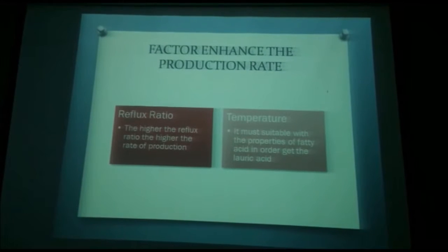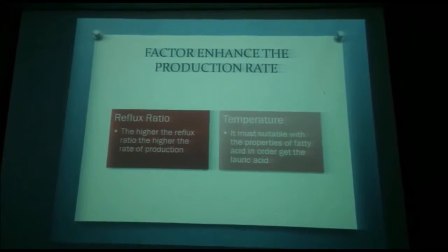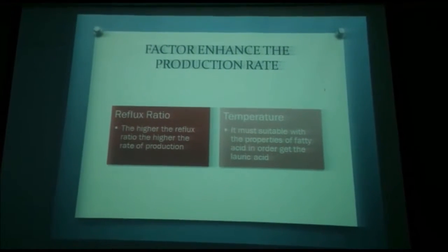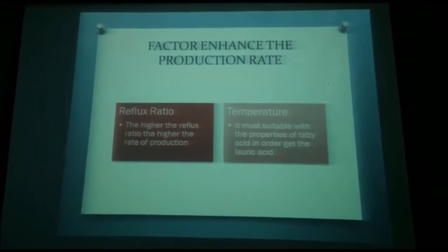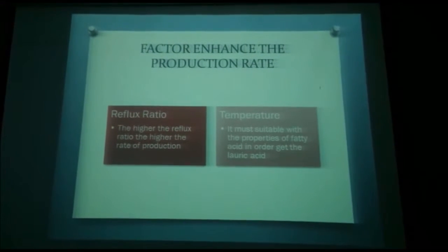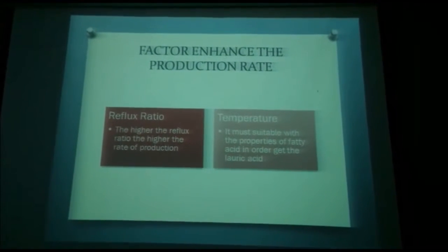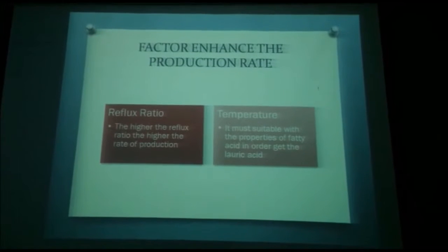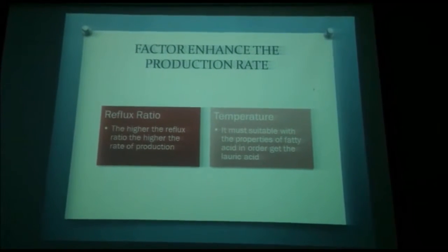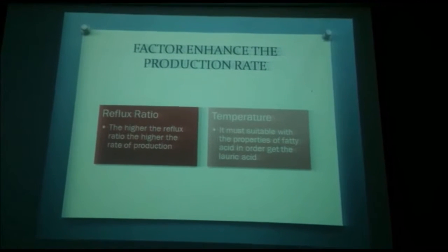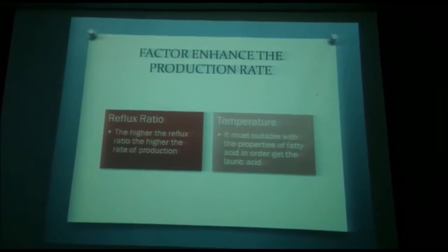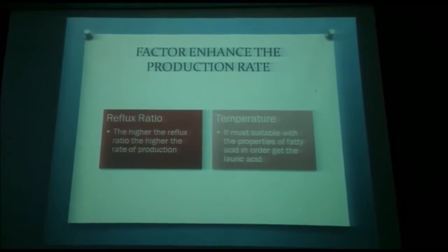If the feed and the bottom temperature are too high, too much heavy vapor will rise up the tower and contaminate the side stream product. This condition combined with a high reflux rate will again lead to flooding and poor separation. The opposite condition can lead to liquid starvation across the tray, and again a very upset process will result.